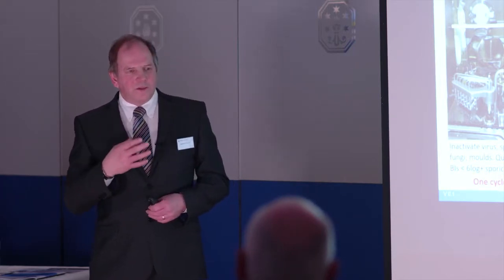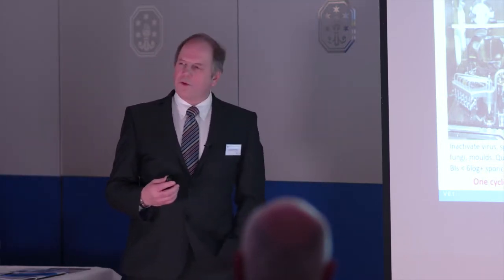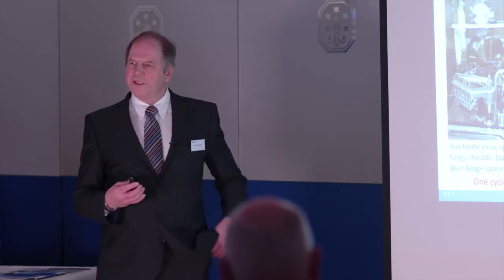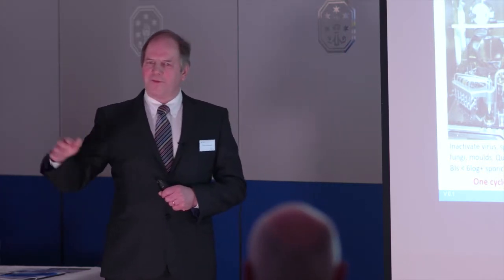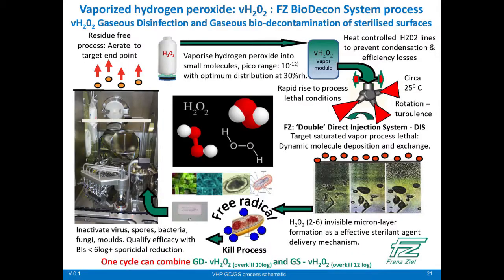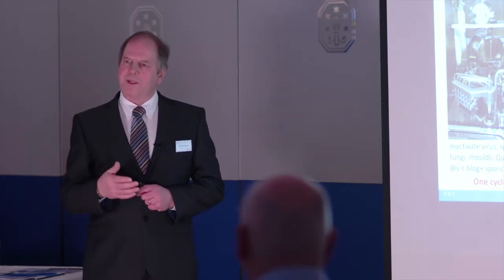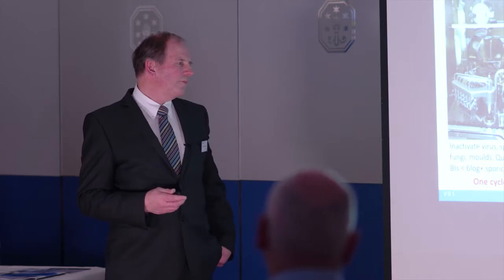So we need to take the vapor through return air ducts and other places to make sure that we have a very secure boundary. A HEPA filter is never a single plate or membrane. It's a labyrinth. It's not a surface. So to get penetration through all that labyrinth, you need to actually pass vapor through it. Putting a BI, a biological indicator, on the upstream side and saying that filter has been activated is some data, but it's not assurance for sure.